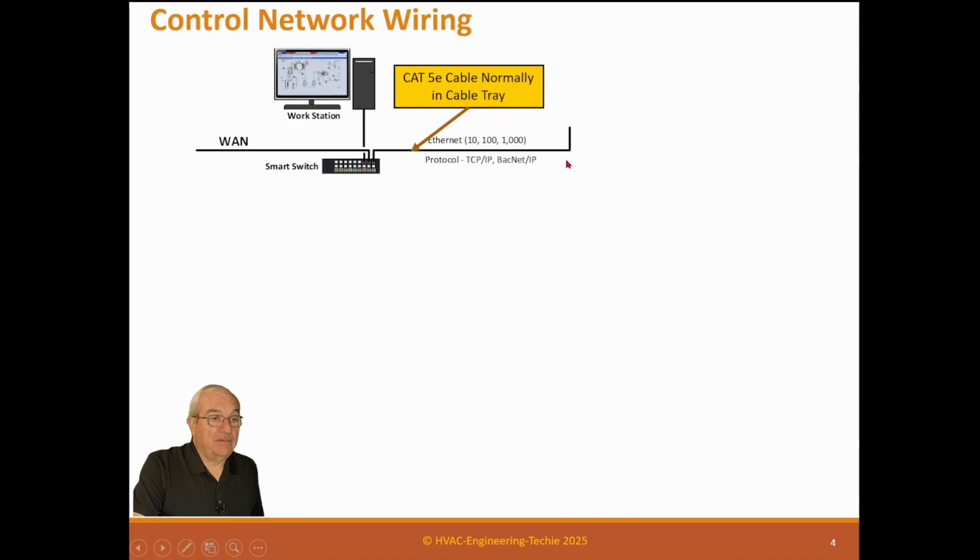And my strict advice is to never put a cable in a cable tray. It seems like it'd be the place to go, but the problem is that the data cable people own that tray, and if they find a foreign cable in it, they normally just cut it out. So you don't want to do that, because they keep track of their cables very closely, and you don't want to have a damaged cable.